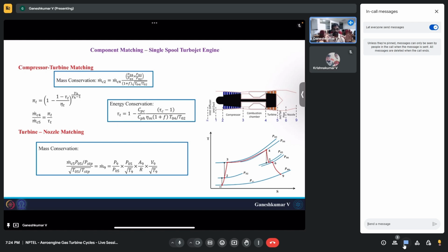But as a separate component, everything can work at all the mass flow rates. But all these components are connected together. You have certain constraints of the nozzle that will ultimately affect the inflow of your engine, and also all the components in between. Okay, so that is the idea that we are trying to capture using this problem.